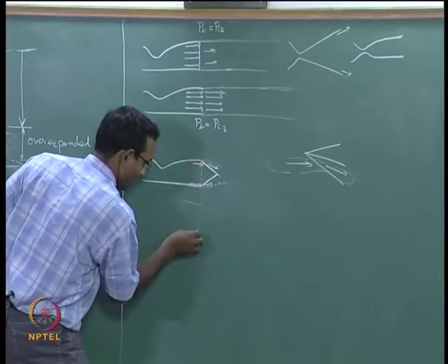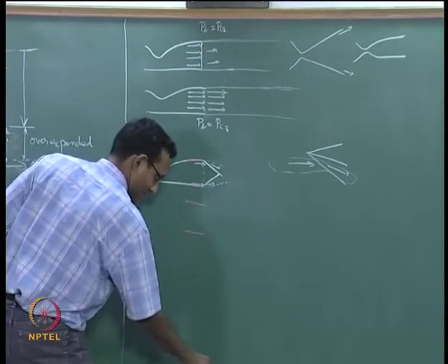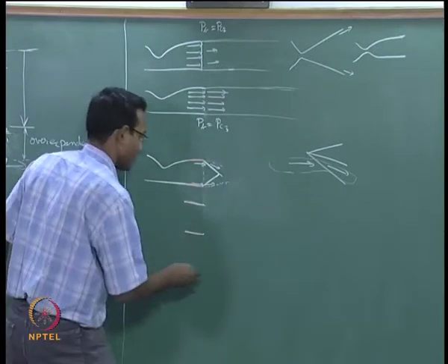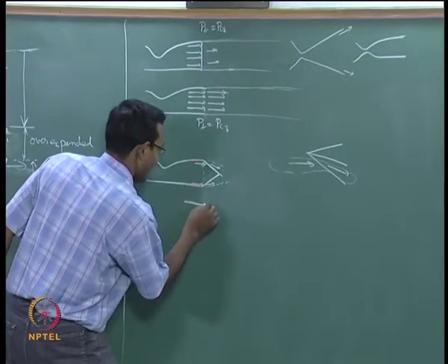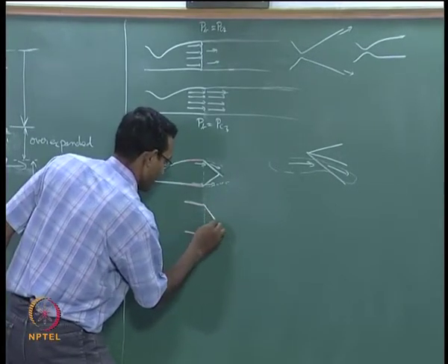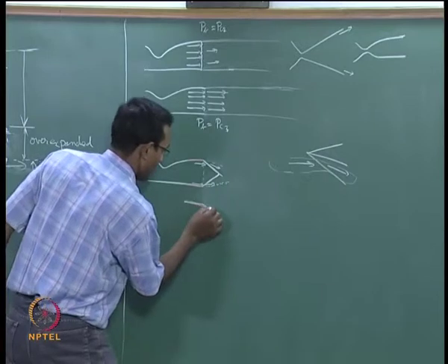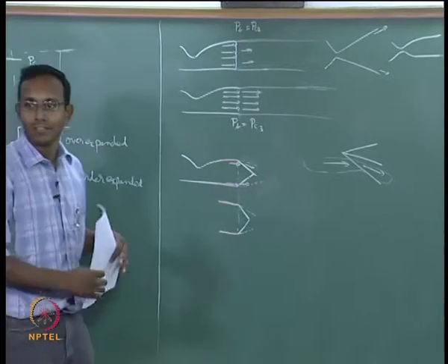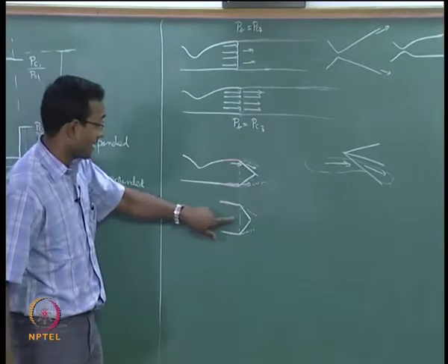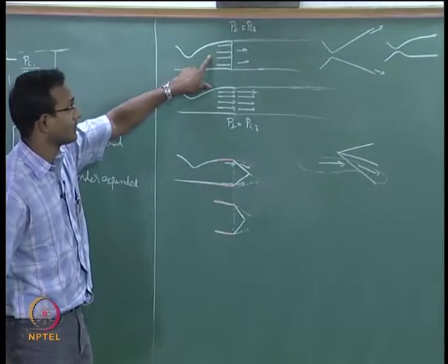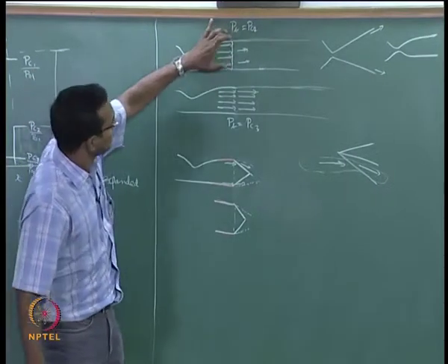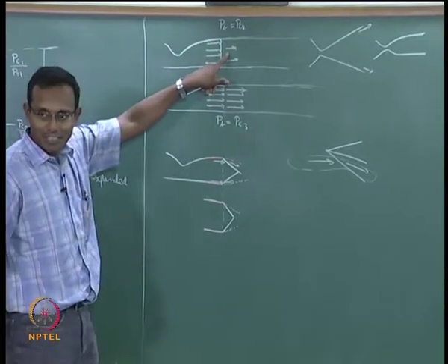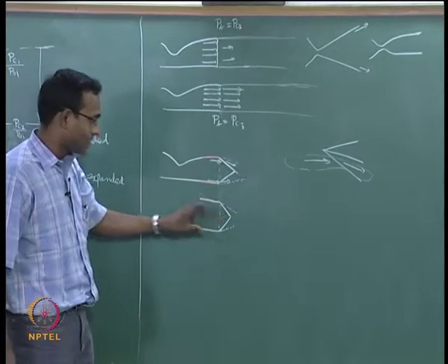Okay, if the shocks have to be strong, I will draw the picture again here separately. This is my nozzle, looks like my chalk writes very thin. Maybe I will draw this in white only, you guys can manage. It will become a lot more strong, and the jet boundary will be shrinking faster, okay, that is what will happen. If you think about the case before this, it must have been this, where the normal shock is there, the jet is going very straight. Immediately after that if I decrease pressure some more, it jumps to this case where it is shrinking a lot,